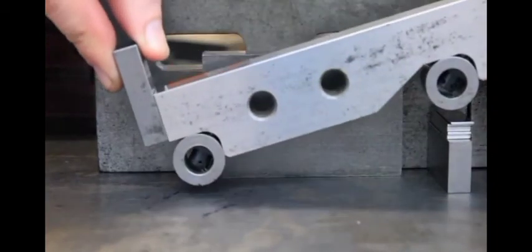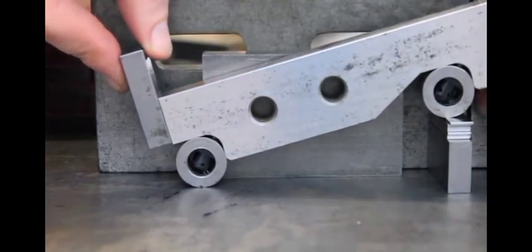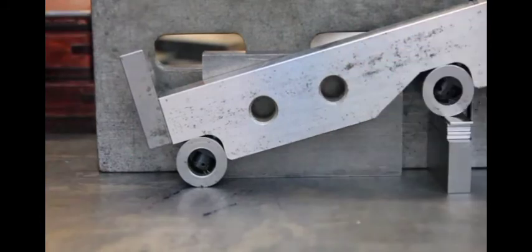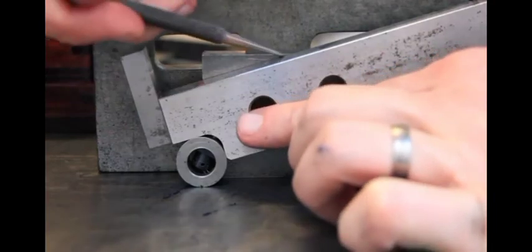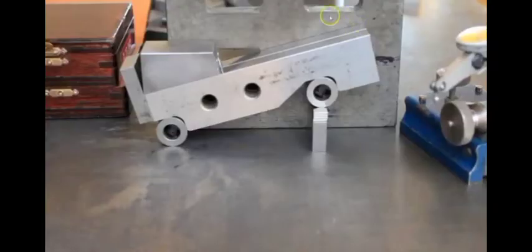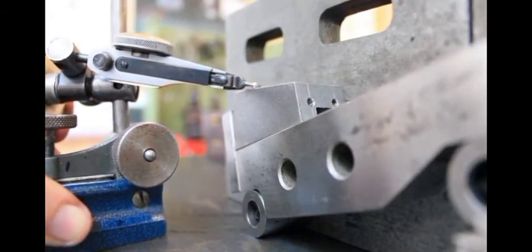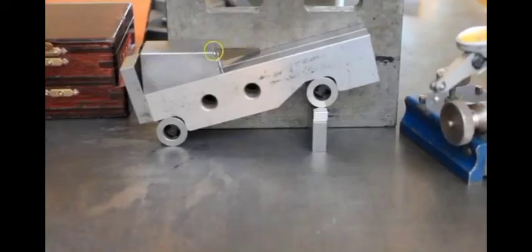The principle of this is that we're going to create a stack of slip gauges on the right hand side, incline it at an angle, and then the sine bar can be used either to scribe lines in layout or to inspect angles with a dial test indicator. So this is an image of what we're trying to achieve. We're trying to incline the sine bar at an angle of 15 degrees so that when we run the finger type DTI across the top of the surface, we can check for any movement, and this surface should be flat.